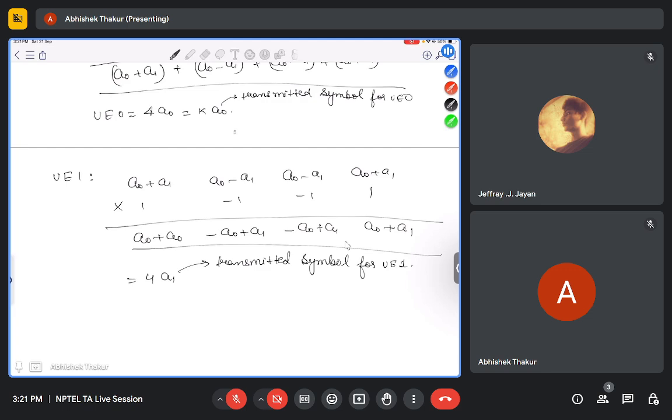So code division multiple access is summarized as multiplying, or modulating, the symbols of different users with their corresponding assigned unique codes, and then combining or adding the code-modulated signals of all the users to form the composite signal, and finally correlating the composite received signal x at each user with the corresponding code, and then they receive back the symbol transmitted to them.